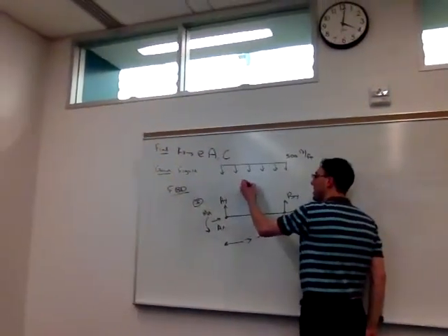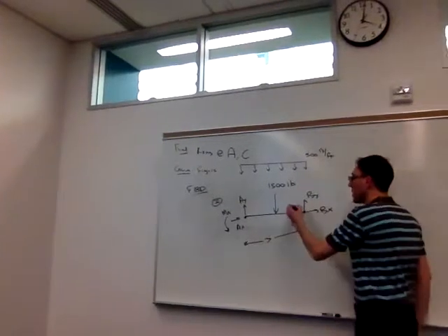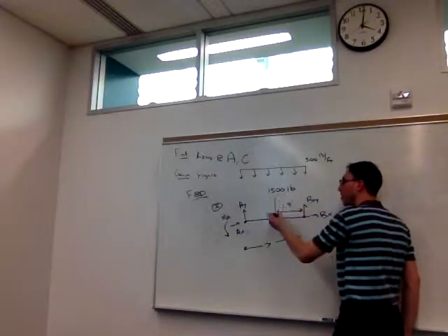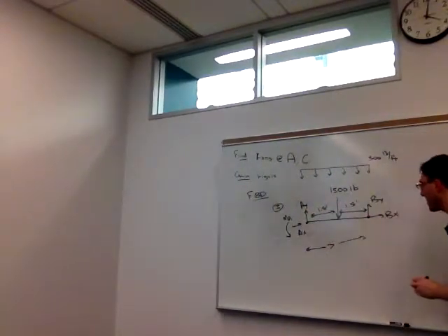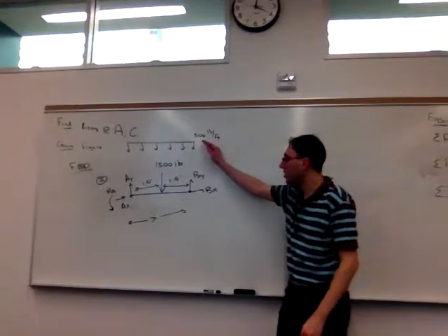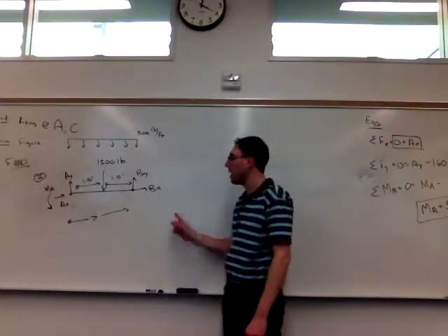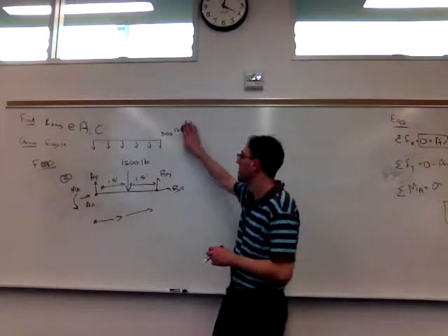So this beam only experiences 1,500 pounds of that total amount, and it will act at the center of this amount of the distribution, the 1.5 feet. The distribution does go on, but this beam doesn't know it directly. BY would include that information, though.